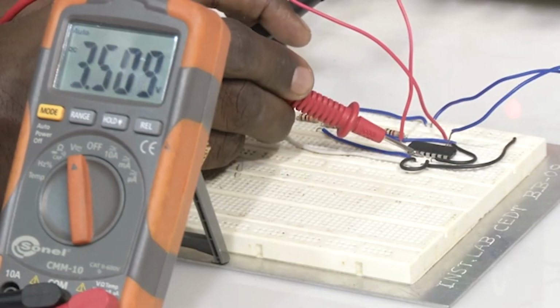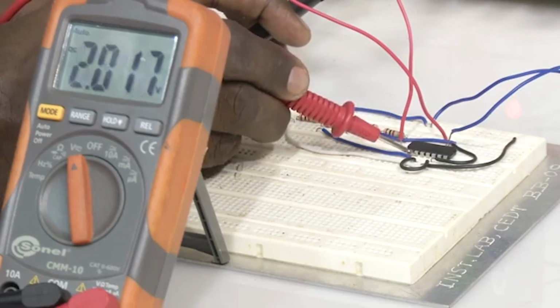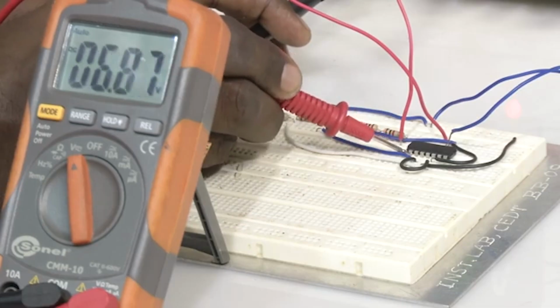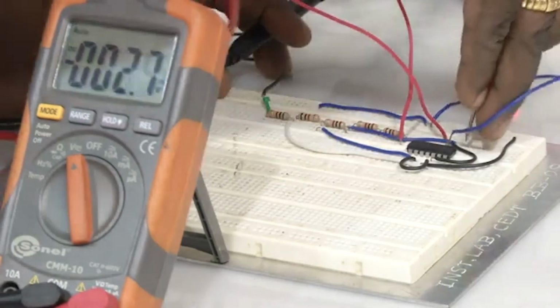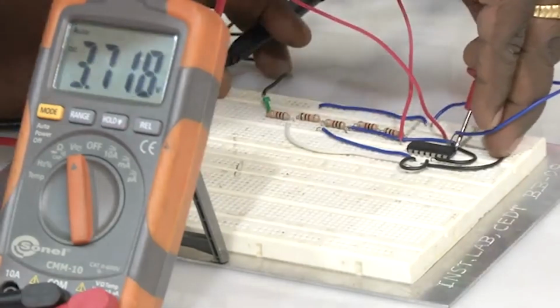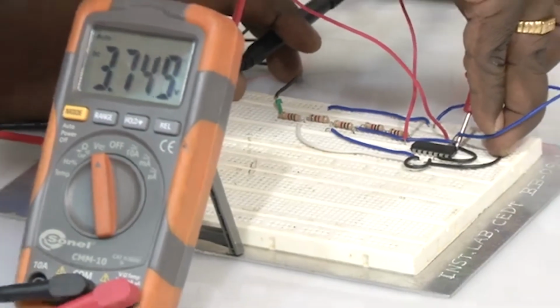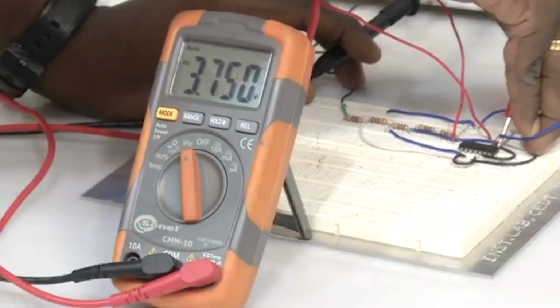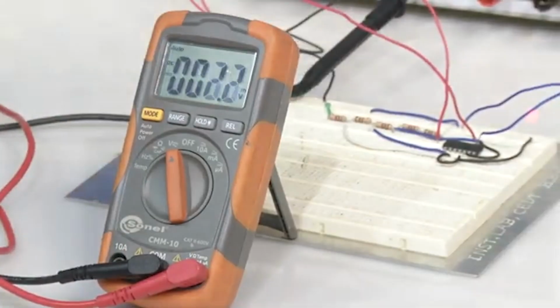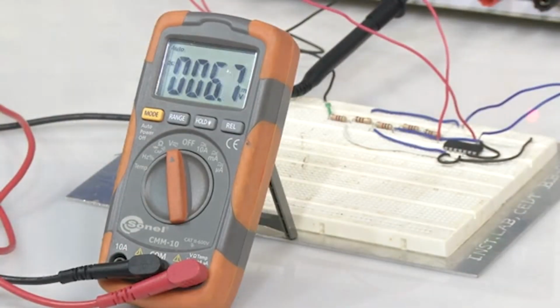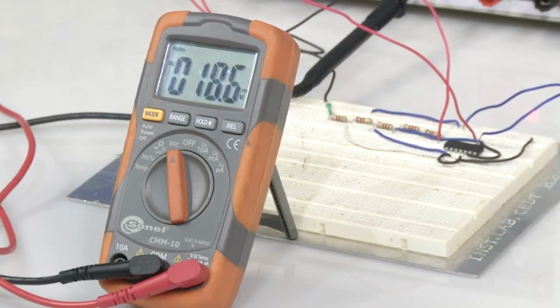This is also 3.5 input V in the positive terminal, this is the negative terminal 2 volt, the output is 3, this is also plus VCC. When it comes to op amp 3, the output is even 3.75, which is also 1. So, that means we understood that when the input voltage is greater than 3 volts, which is in the final level, we will get an output C1, C2, C3 as 1, 1 and 1, which are nothing but plus VCC, plus VCC and plus VCC.